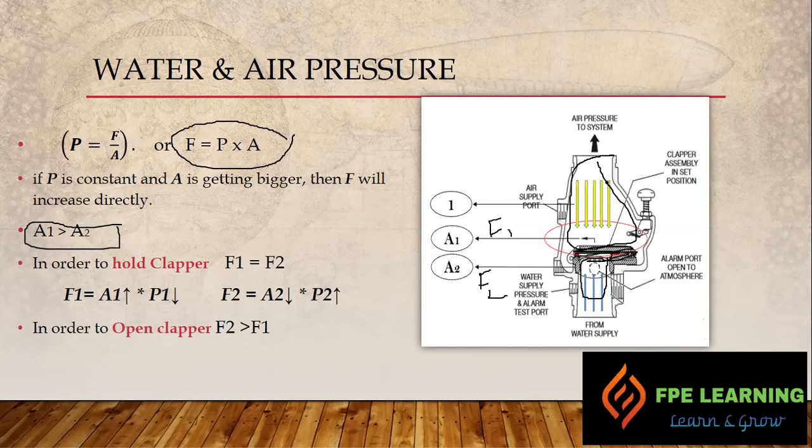So at this moment, the pressure on this side will decrease, and once the pressure decreases, the water pressure will push the clapper and it will open, and the system will activate, causing it to extinguish or control the fire, right? This is the basic idea.